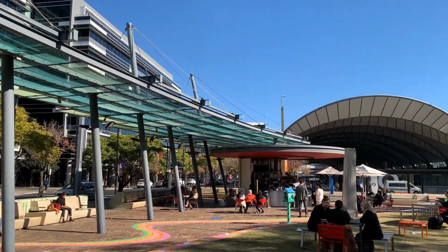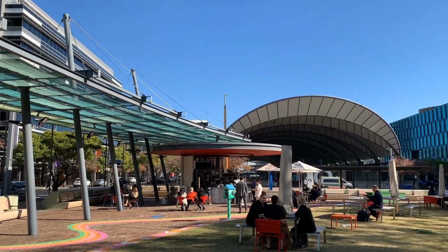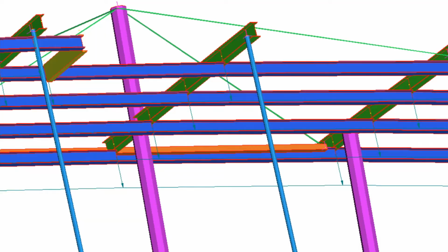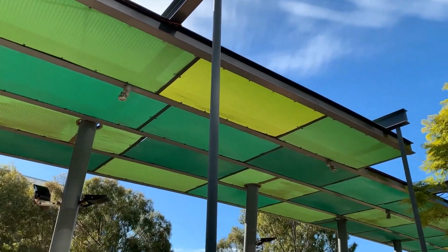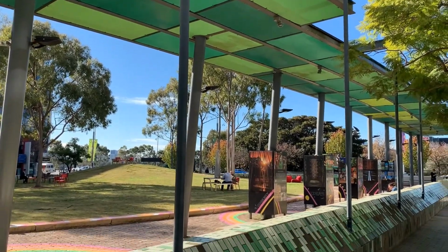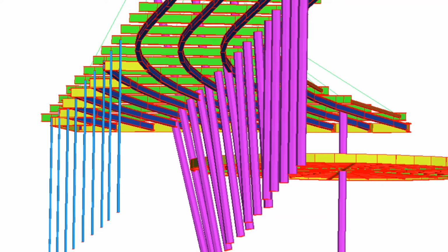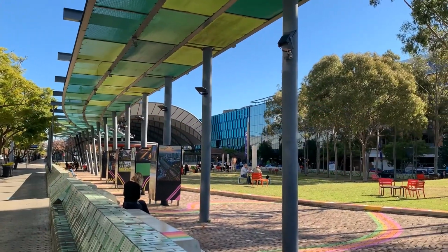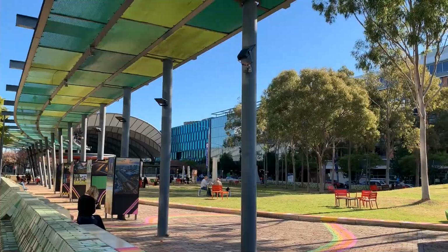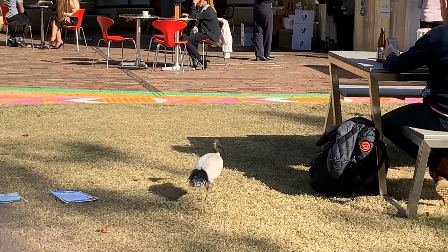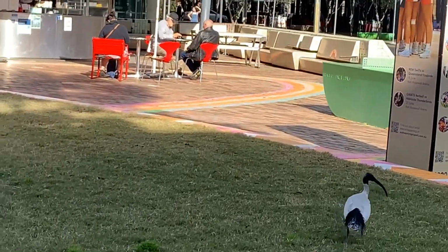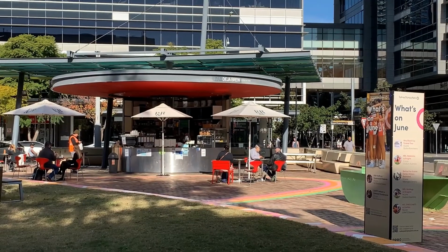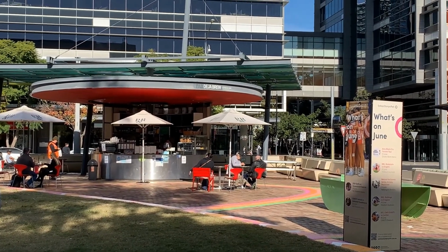Members can only withstand a certain amount of elongation before they fail. Linear analysis requires only input of Young's modulus and Poisson's ratio. The software assumes the material only has elastic deformation. The design engineer needs to check the maximum deflections and stresses to see if any members will fail.